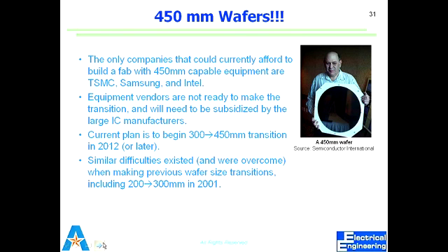Think about it, even a chuck which we use to hold a wafer, you cannot use a 2 inch wafer chuck with a 4 inch wafer, because that will have too much vibration once you rotate it at 4,000 RPM, for example. Does that actually create process difficulties? Like, does your spin coating still work with the same chemicals when you've got that much area? Okay, so that's now the chemical side, right?